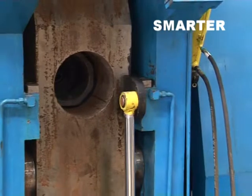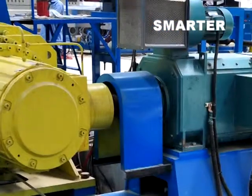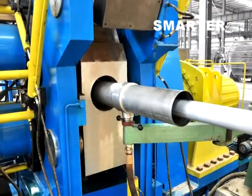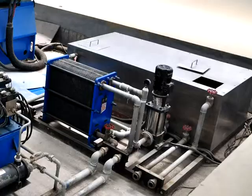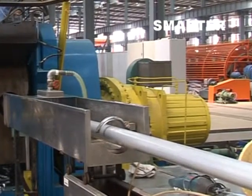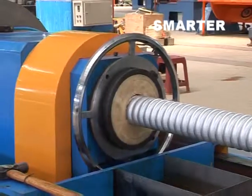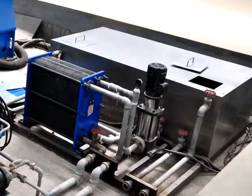Main extruder is consisted of motor, reducer, extruder, and stand. It is driven by DC motor, transmitted through the reducer to main shaft and extruding wheel of extruder. Hydraulic system, lubrication system, and main machine cooling system is serving for normal running. In hydraulic system, extra high voltage device is used for compressing the die block. Cooling system of lubrication and main machine cools lubrication and cooling medium by heat exchanger throughout water circulation.